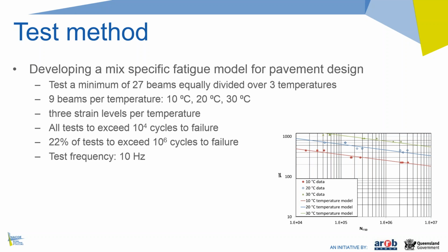I'm just wondering, Eric, those 27 beams, I understand we had 5 beams for the modulus testing. Can those same beams be used for the fatigue testing, or is this another 27 beams? Yes, there's nothing in the test method to stop you from using those same 5 beams. I wouldn't necessarily encourage you doing that, because I would be worried that you have imparted some damage on those specimens through the modulus test. But the test method actually allows you to do that, because it's based on the European test, which also allows you to do that.